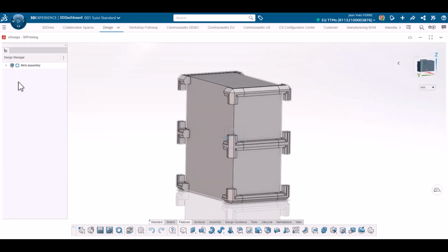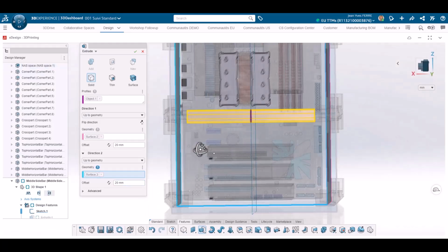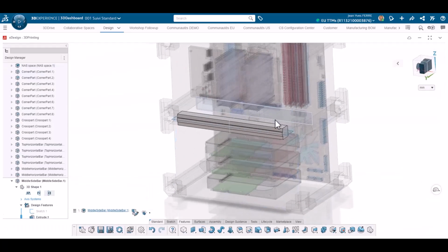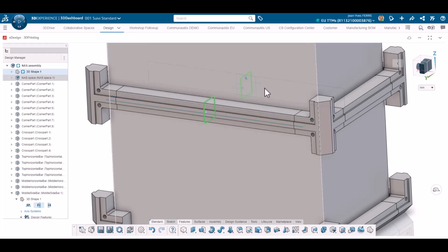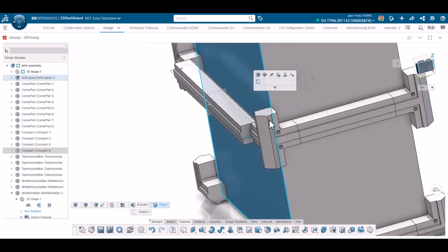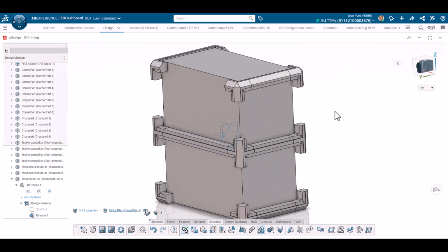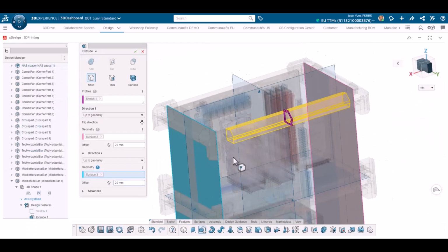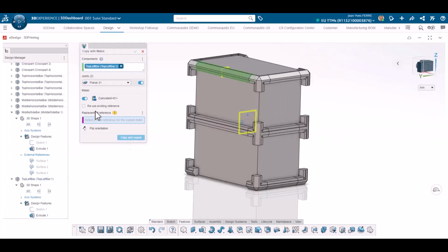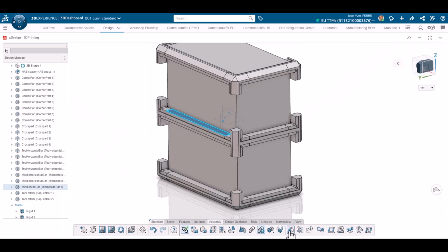Retrieve the sketch from the cross part, create a middle extrusion up to the cross parts to adapt if anything changes, and add mates to this transversal part. Remember to mate parts you create with external references. External references are never enough to fully define position of a part, and it could lead to issues when a drastic change occurs. I do the same for topside bar, following the exact same process for the sketch and extrusion end conditions. I copy the top bar on the bottom with copy with mates, and I'm ready to mirror those parts on the other side.